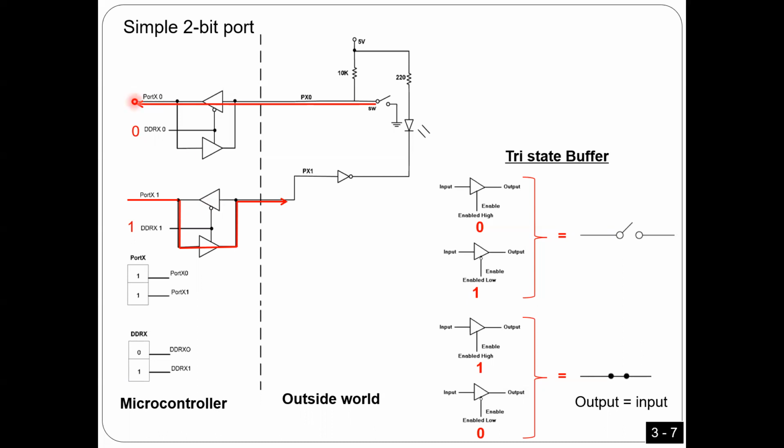Simply, as you see in this figure, when I put 0 here, you actually are going to connect this one. This one is open. That means, because this is a switch, the circuit is going to be connected this way. The electronic circuit is going to be connected this way, okay? So this 0 is coming from the data direction register, as I told you. Here, if you put 1, the circuit is going to be connected this way, as you see here. That's why here I'm putting LEDs or output devices. Is that okay, guys? Any questions?